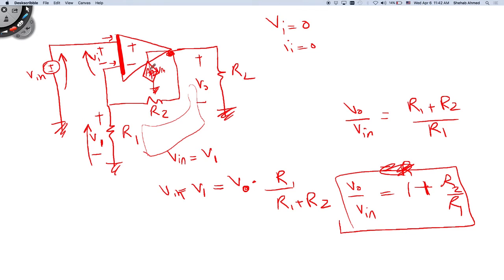There's nothing here. So the voltage at the output is defined really by the external circuit. It has nothing to do with the load resistance changing. What does this mean for the output impedance? Output impedance is also 0. So we calculated the gain, we know the output impedance.